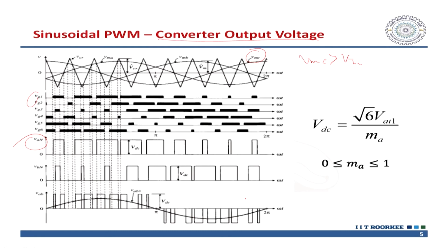Please understand that you require to provide an inductor. Why? Because ultimately this sine wave, the volt area curve, matches with this sinusoid, matches with the pulse width modulated waveform, but there is an instantaneous variation between the PWM voltage and the voltage at this point. So, for this reason we require to provide a buffer inductor, and thus the calculations of the LF, the inverter side inductor, and the grid side inductor come into the picture.